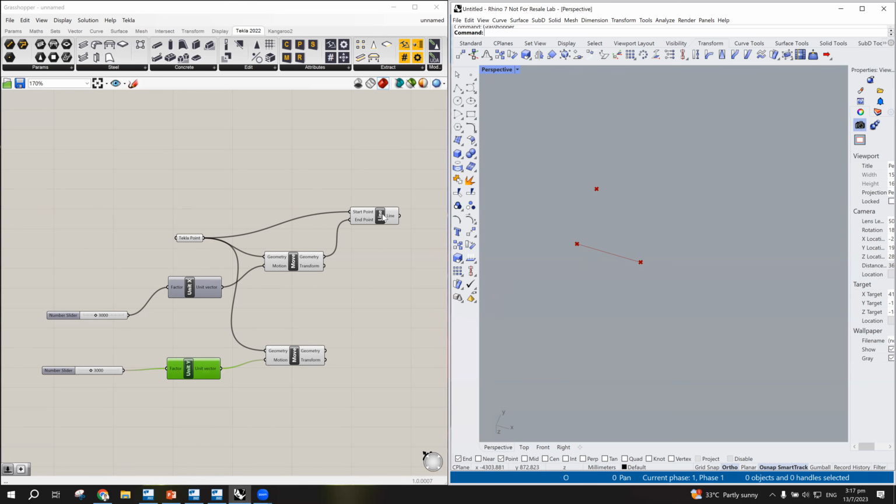Of course, if you want to create a line, you can either type line again, or there's a shortcut to copy this one. You don't need to write, you don't need to Control C to copy this. You can duplicate this line by simply selecting this line, holding, and then pressing the Alt key, and there you go.